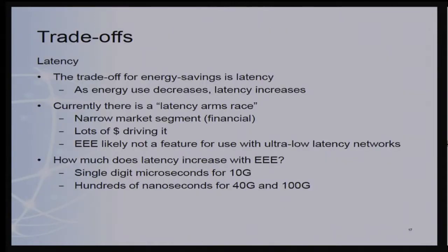Now the trade-off, if it isn't obvious, is latency. It takes a little bit of time to wake up the receiver. So as energy use decreases, latency increases. And there will be some cases where you may not be willing to accept this increase in latency.